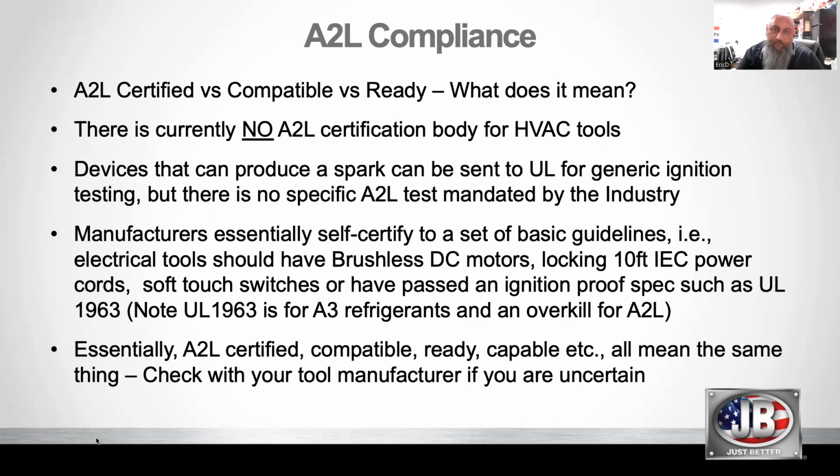They don't mean anything. There is no body for A2L certification of tools at the moment. You can send an item of equipment to UL for ignition testing, but it's an ignition test. It's got nothing to do with A2L. It's a standard ignition test. So, for example, JB manufactures a recovery machine, the F6 Boost, and that has been tested by UL for A2Ls and A3, but from an ignition perspective, right? It's not a specific A2L test.